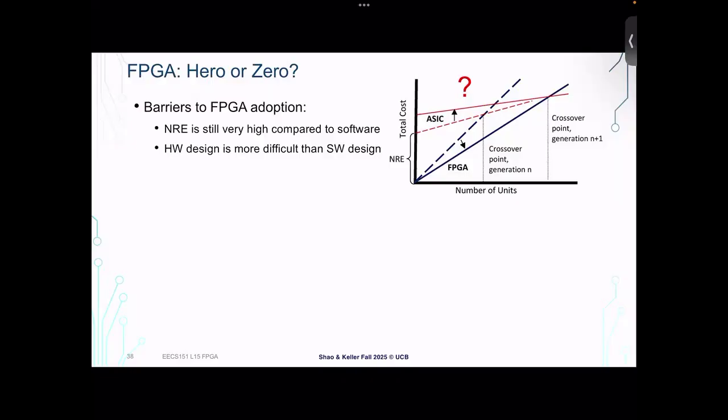One is that, this whole idea of ASICs have really high NRE and FPGAs have very low NRE. I think in practice, that's not true because mask costs, the cost of the physical tape out is one part of NRE, but especially in a modern complex design, the engineering work needed to build the thing is the biggest component of NRE. And in particular, to verify the thing is the biggest component, right?